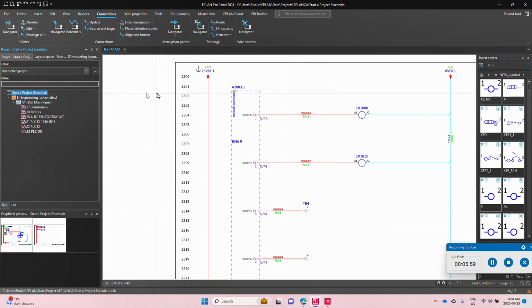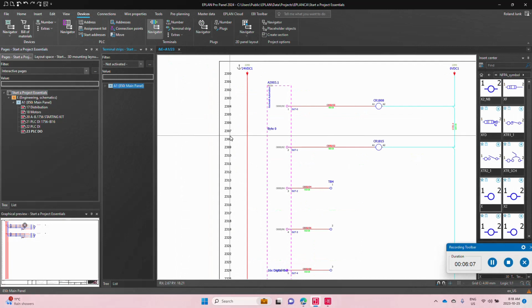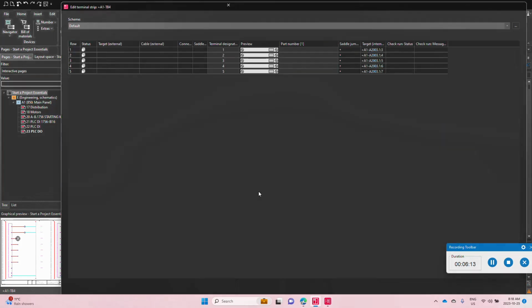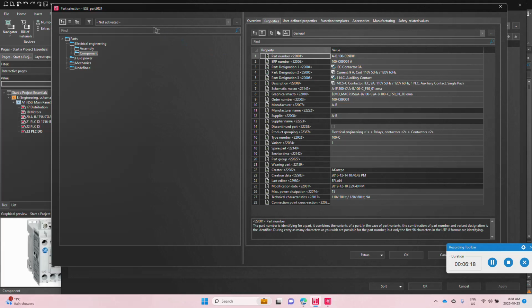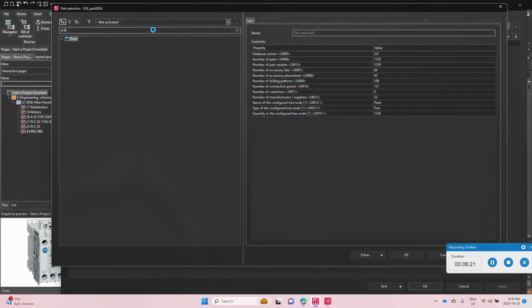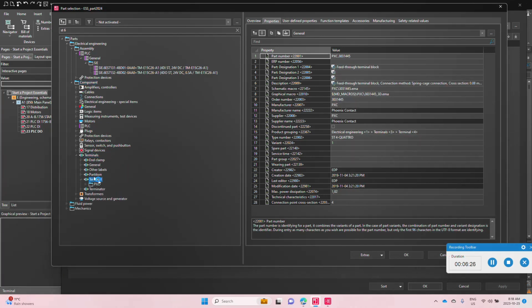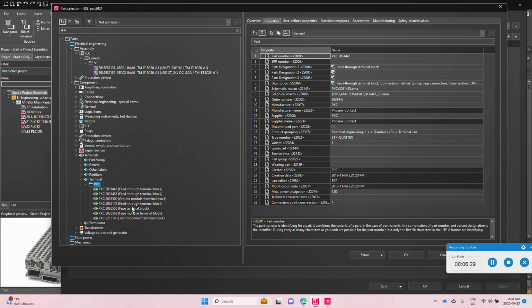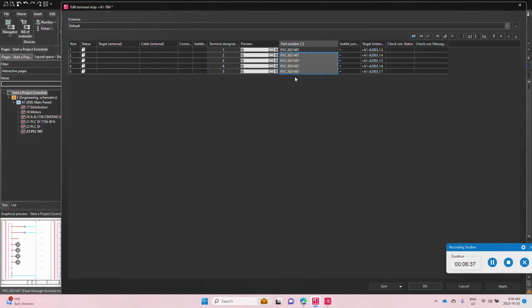The other thing that we have created is a very smart, intelligent PLC interpretation. On top, we also created the same with terminals. Now, the terminals are, in essence, very simple connections. Now, these simple connections very often are assigned with a part number, and you can simply go here and pick a part number. In this case, I want to pick a terminal, more specifically one from Phoenix Contact. I'm going to use the regular ST6 terminal like this, and this is a pre-assignment I will do for these